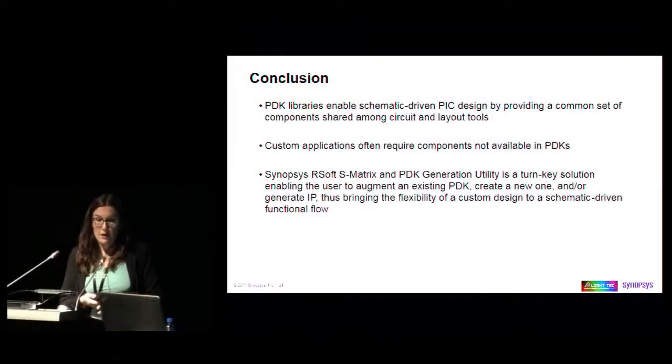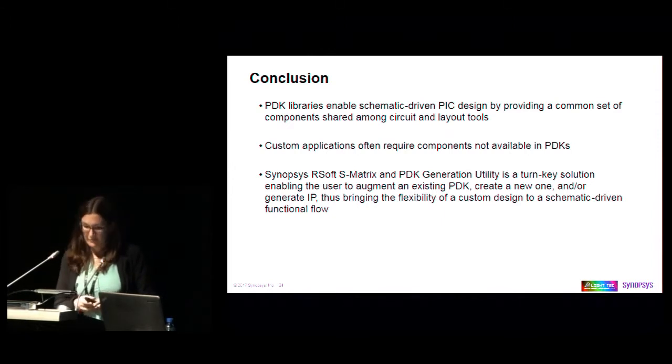And in that case, you will need access to another design flow process, and one of them could be Synopsys RSoft tools, and in that way you will generate your own custom PDK from components and then go to the schematic level in order to study the full PIC inside RSoft, following the foundry technology rules that you have available from the foundry. Thank you for your attention.